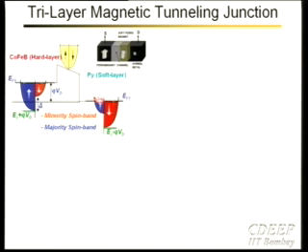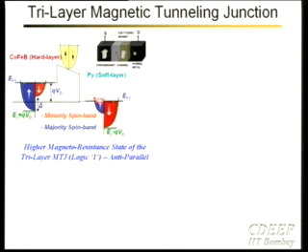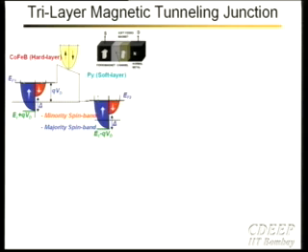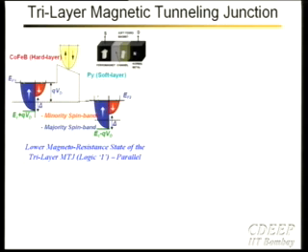And if you look at the ferromagnets, they have some interesting characteristics. If it's predominantly upspin, then the E-k diagram shown on the left is what you're going to be seeing, versus if you have one where the minority spin is the upspin, you're going to look at the one on the right side. The interesting thing that happens is if you inject, for example, an upspin, it's going to go in, but since the right side is dominated by downspin, it'll get reflected. One can show that you're going to get a resistance in the anti-parallel configuration which is going to be different from when both were upspin. If they're both upspin, the electron comes in, the right ferromagnet is also upspin, and it's going to go through. Due to that, the resistance in the two configurations, anti-parallel and parallel, is going to be different.